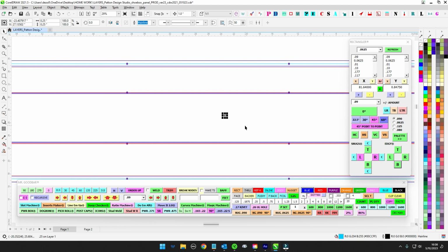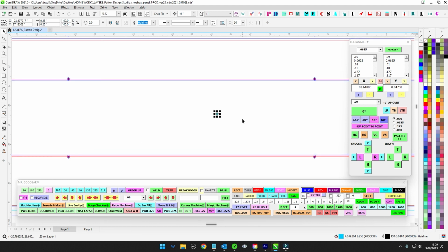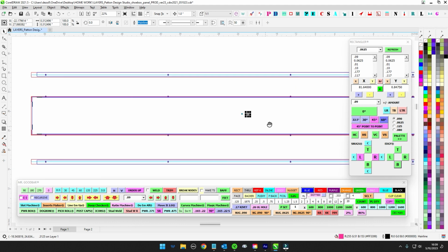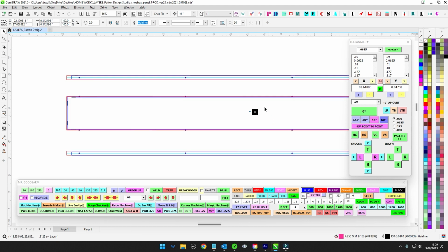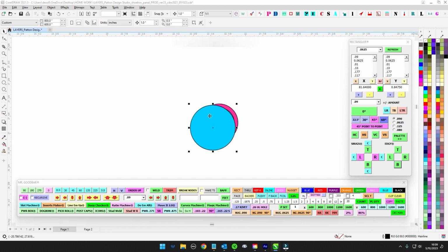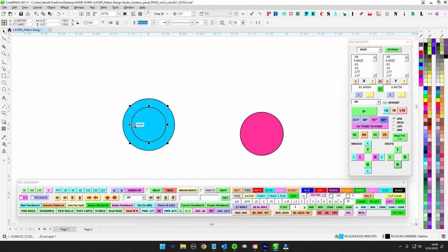That being said, if this is going onto a stucco exterior wall or a brick wall, then they're going to favor 1/4 inch blue Tapcons, aka blue screws. Masonry screws, which are 1/4 inch diameter. So then you're going to want to step this up to a 5/16 for exterior. Now that might not even be enough, because when you're trying to hit a screw hole exactly on a stucco wall or a brick wall, these are going to wander. So sometimes a quarter inch blue screw into a 5/16 hole is not enough. That's when I will do maybe a 3/8, because they can always put a washer on that, and it gives them the maximum amount of leeway.